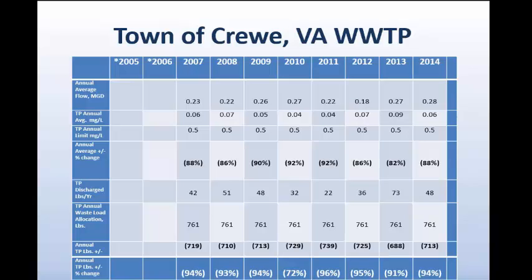Once we started using the liquid molasses product that is also fortified for enhanced biological phosphorus removal, we were able to realize phosphorus removal that allowed us to drop our alum usage significantly. And as you can see across the very bottom, we're looking at total phosphorus pounds on average about 95% below our allotment. As total nitrogen pounds realize financial gain, so does total phosphorus.